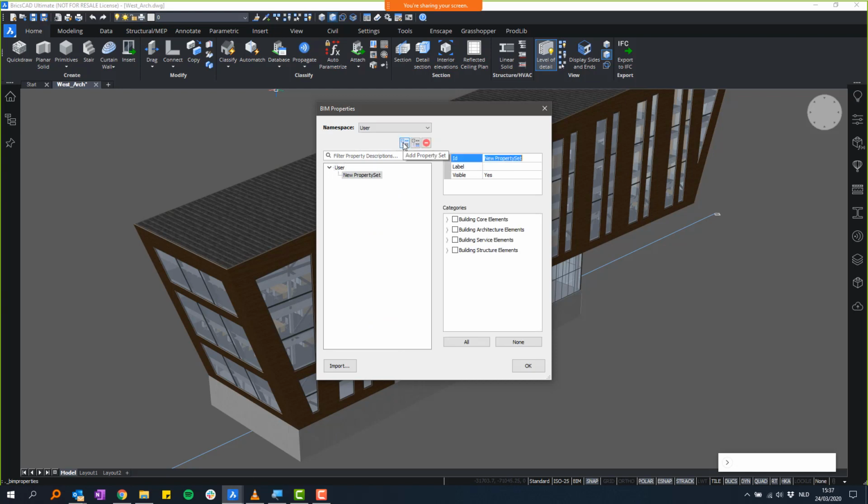So let's say I make a custom property set. Custom properties Windows, for instance, and assign them only to Windows. Like so. And inside this set, we can add properties. For instance, the cost, like integer or real, for instance, and manufacturer.